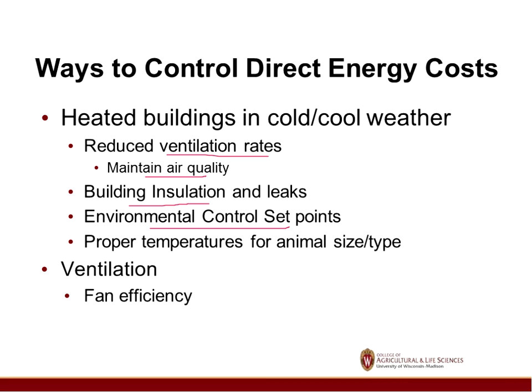Environmental set points. Again, this gets back to temperature. Make sure we've got our temperature set points and our offsets, and when our fans are coming on, placed in the right areas so we're not overventilating or overheating, etc. And I already mentioned temperatures and fan efficiency. Make sure that we're doing the maintenance on those fans, and that the fans we've selected are high efficiency.